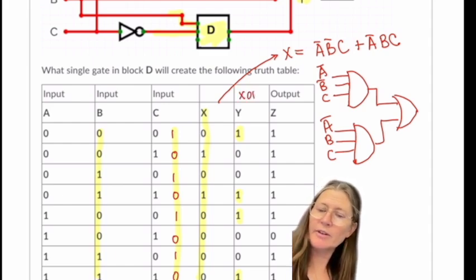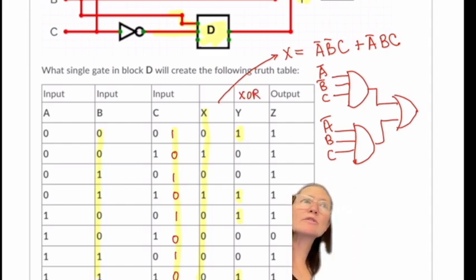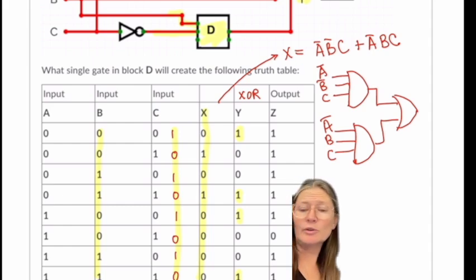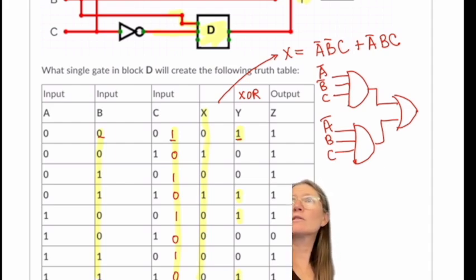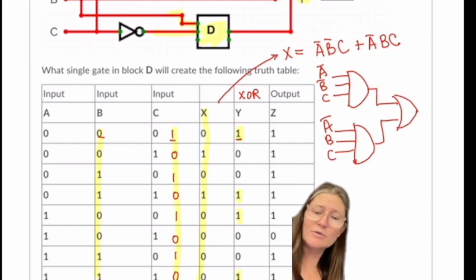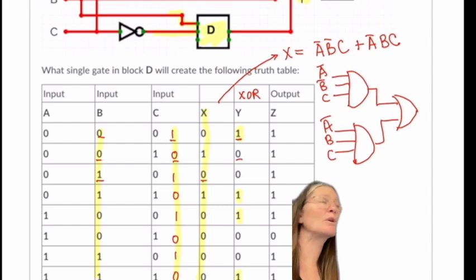I had somebody say XOR. So one way you could do this is rule out some of them. So you see here you have a 0 and a 1, and then your output is a 1. So that gives you the possibilities of which gates? Or an XOR. So then you would go to the next one and you say, oh, it's a 0, 0, 0, so that still matches both. A 1, 0, an OR gate would be a 1 out, but this one has a 0 out.